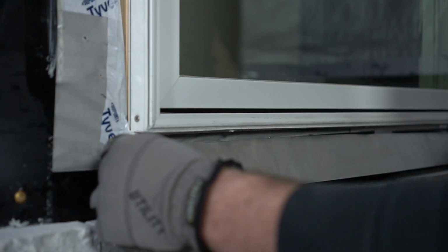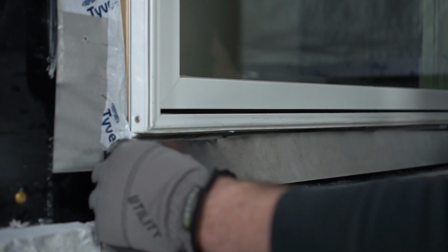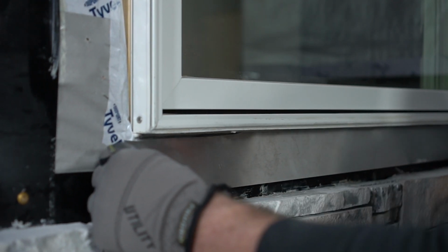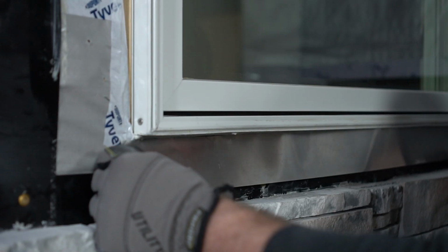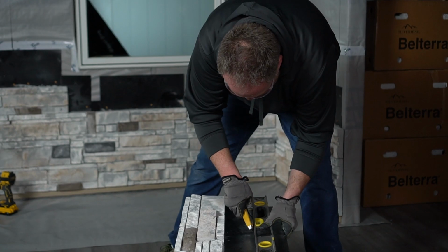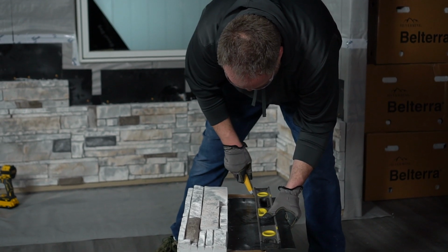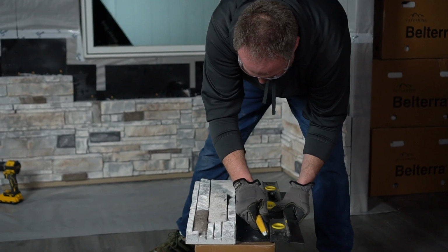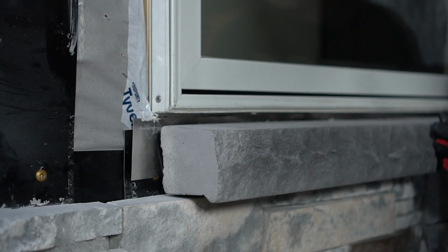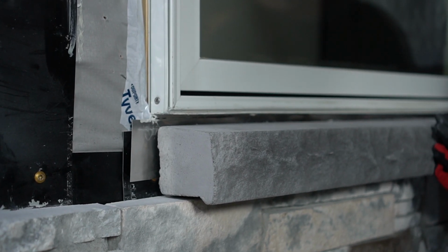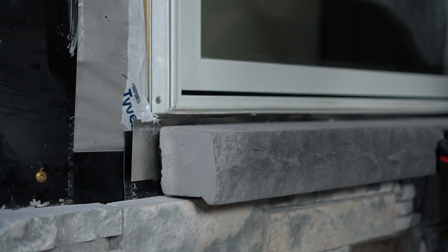Cut supplemental unpainted aluminum flashing to fit snugly against the bottom edge of the opening, covering visible breathe holes. Bend the sill flashing back on itself so the flashing folds down and is flush with the back of the sill. Trim the top of a modified panel to fit in the gap between the last full panel and the sill. Dry fit all parts to ensure tight fit, leaving a 3/8" gap between sill and opening.